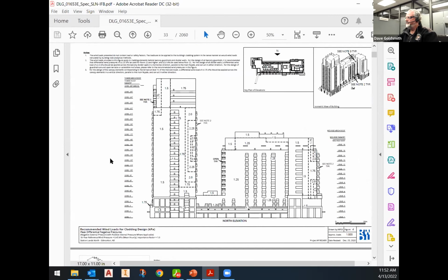Very important, because one of the worst things that can happen is to quote a very large building like this, with a window package costing in the millions of dollars, being unaware that this is happening in the background. You quote the building, you win the job based on a naive set of assumptions, and then the shop drawings come back from the supporting registered professional and they say you need to go from 4mm glass to 6mm glass on the windows that are here, and your mullions need to be extraordinarily heavily reinforced on these windows.